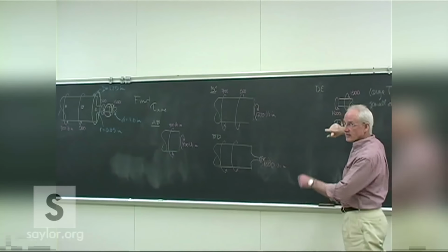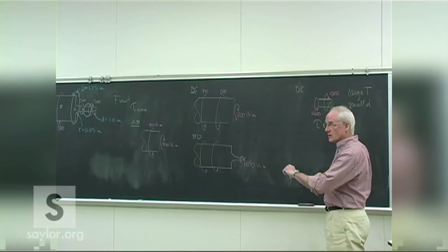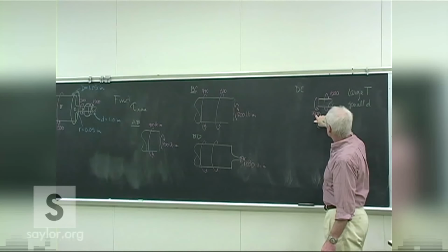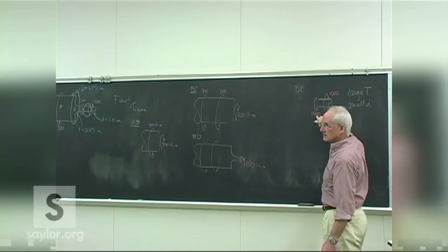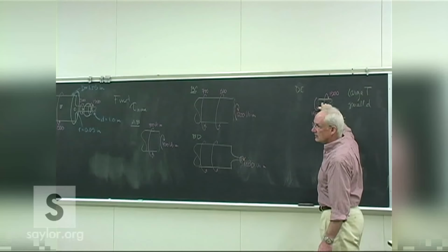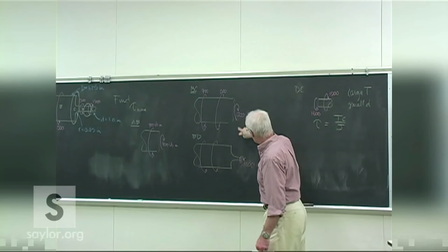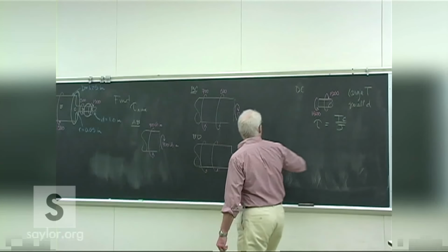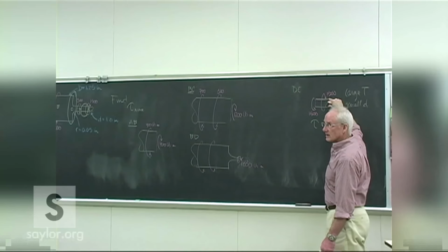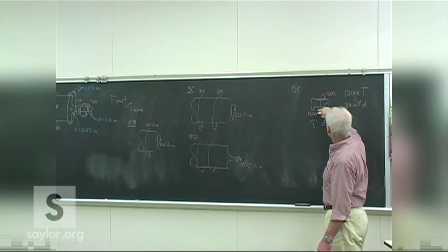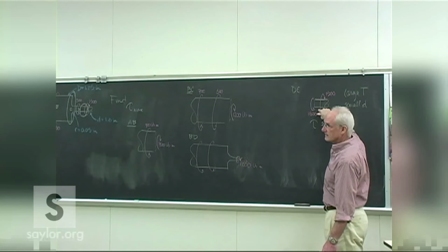The only time direction matters is if we're looking at the angle of twist, where twist can be one direction and the other. Here, all that matters is the magnitude. This is the internal load in that end of the shaft, which is the biggest load of any, and the smallest diameter. So this is a critical area you have to look at.